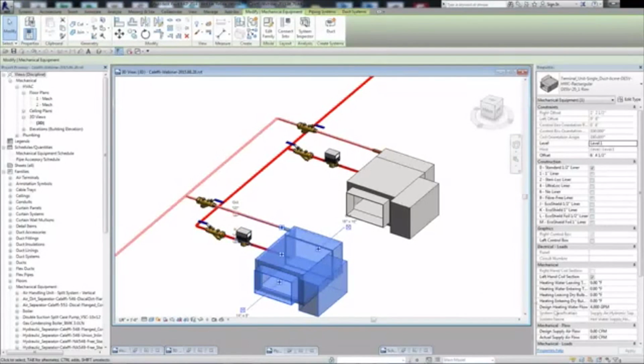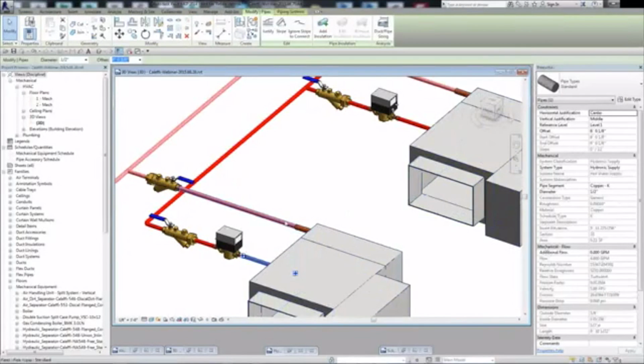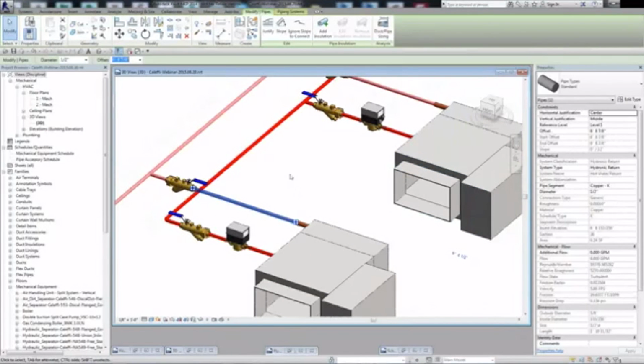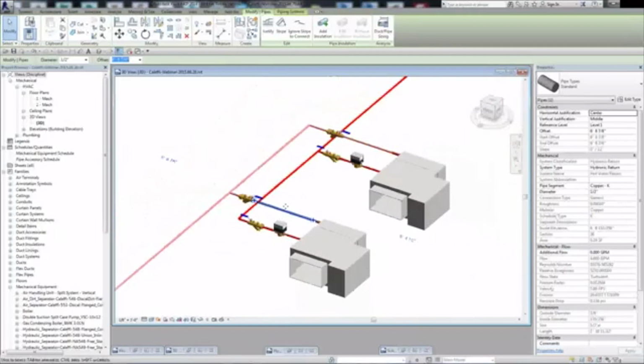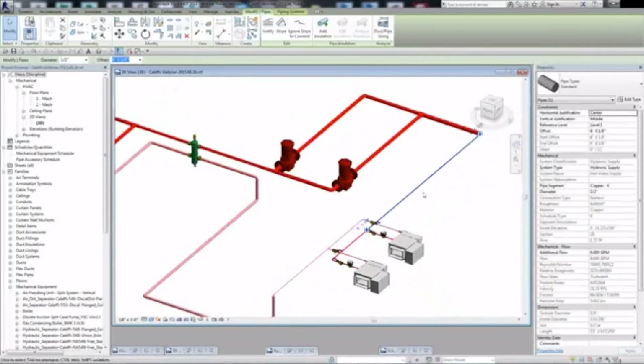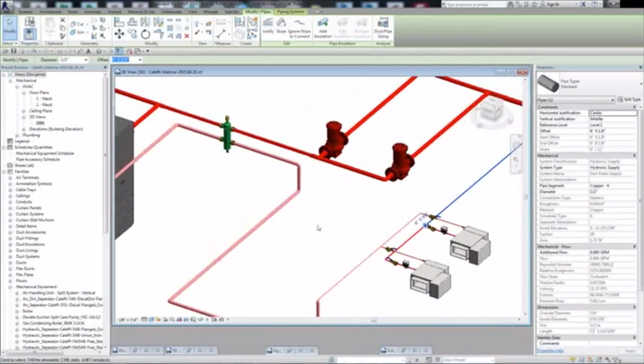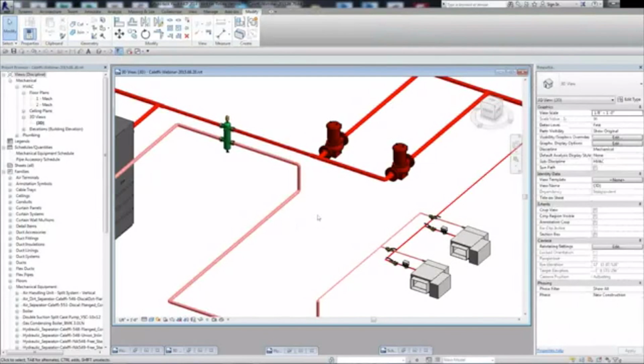In this case, this particular heating flow is set to 4 GPM. So we have the supply down here set to 4, and similarly the return is also set to 4. When these things are connected in tandem, it's going to total. So I should have 8 down here, and I do have 8. Please excuse the rudimentary design here. I know there are a lot more building components that go into a hydronic system design, but this is just to represent how a typical system is going to work.